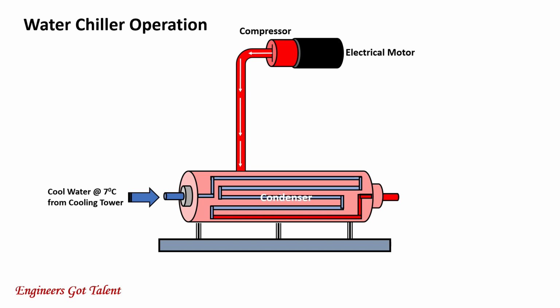The refrigerant, which is outside the tubes, and the water, which is inside the tubes, never mix and are completely isolated inside the vessel. The hot refrigerant then loses its temperature and cools down. As it cools down, the refrigerant begins to condense, turning from hot vapor into warm liquid, still at high pressure.